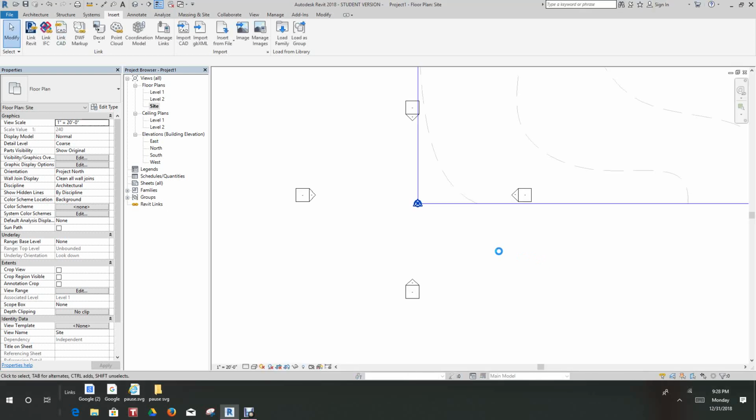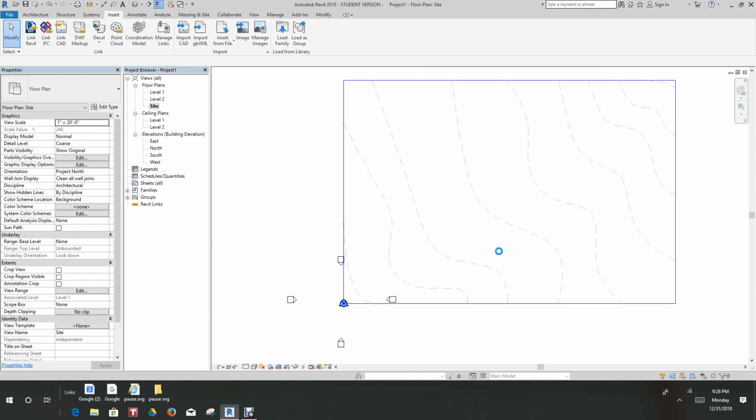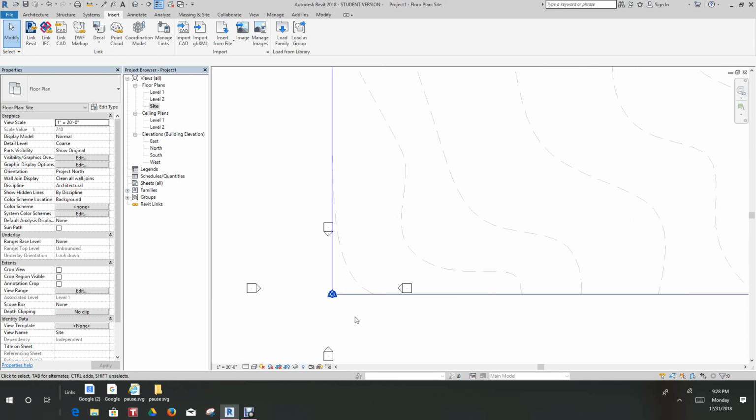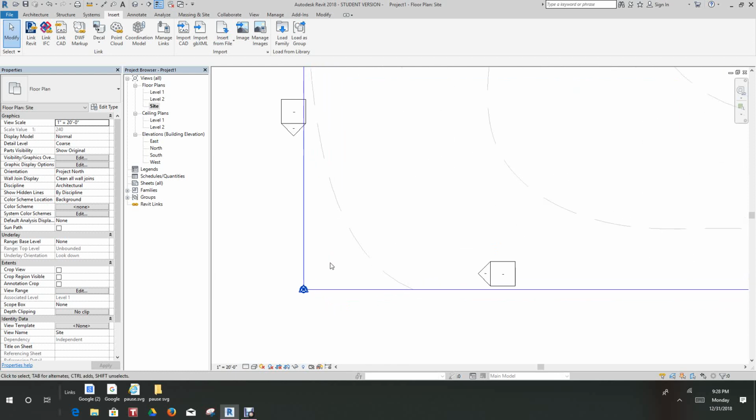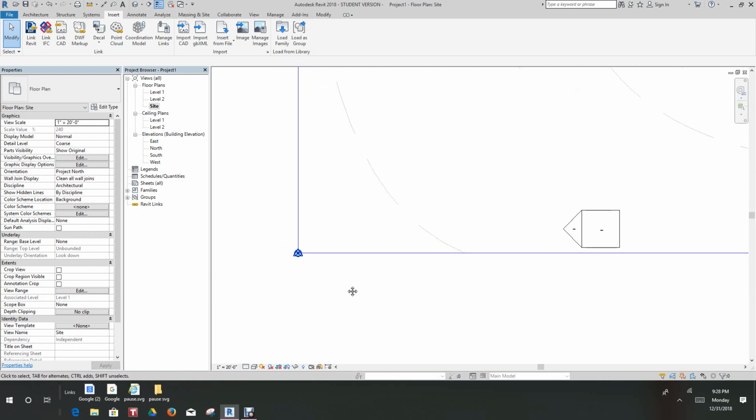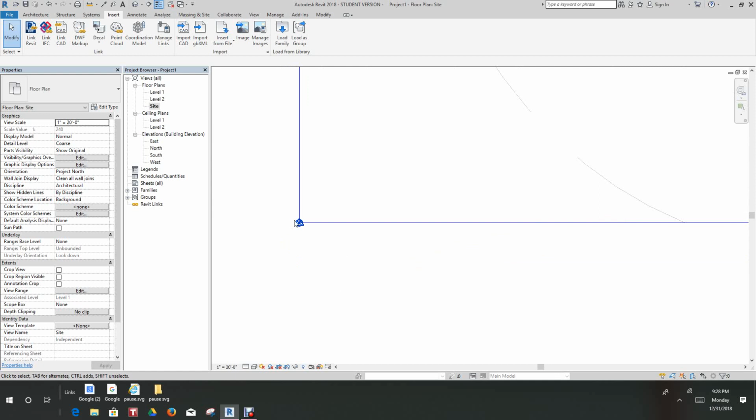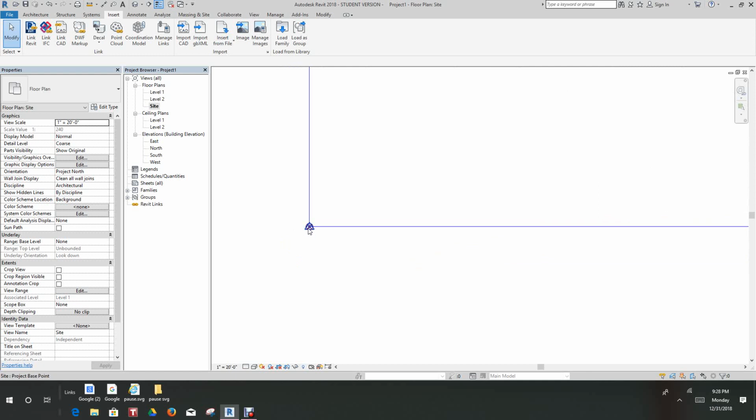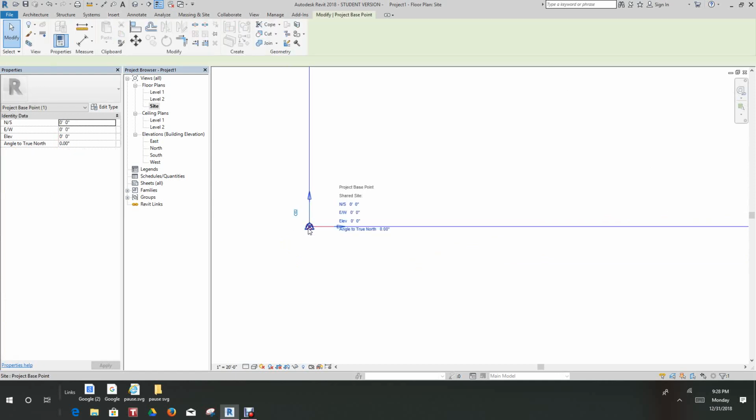Okay, now once we have the file, we want to key in ZE, that's zoom to the extent of the file. Now once we have this inserted into our model, it's an AutoCAD drawing, we want to click on the base point, which is here.